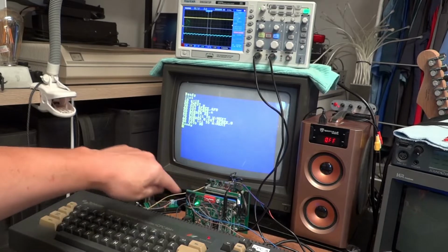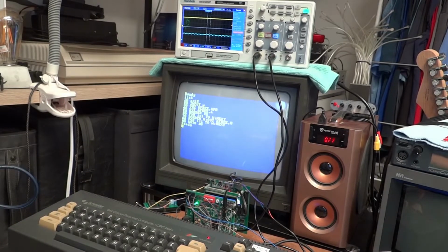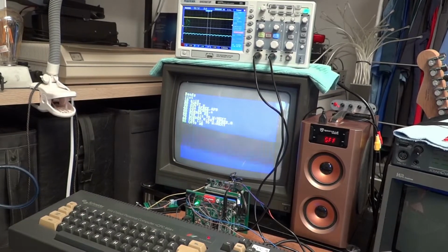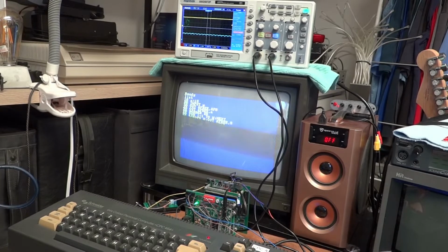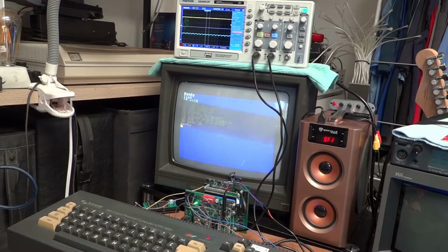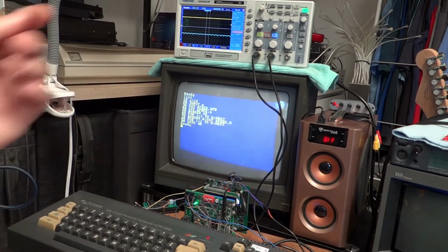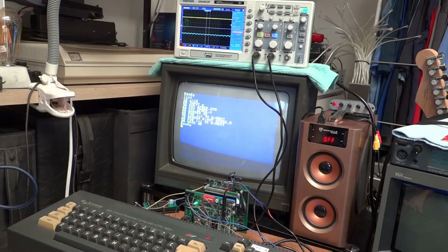This is the LambdaSpeak FS, and LambdaSpeak FS makes it easy to turn on a digital output port. It has a GPIO header here, which is usually used for LEDs, but it's just easier for me to pick up a digitally generated signal from the CPC there rather than hooking up something to the printer port, because I just have that available. So that's channel 1, which is going to be our square wave signal.